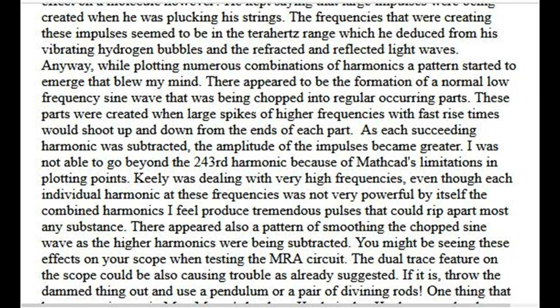There appeared to be the formation of a normal low-frequency sine wave that was being chopped into regularly occurring parts. These parts were created when large spikes of higher frequencies with fast rise times would shoot up and down from the ends of each part. As each succeeding harmonic was subtracted, the amplitude of the impulses became greater. I was not able to go beyond the 243rd harmonic because of MathCAD's limitations in plotting points.